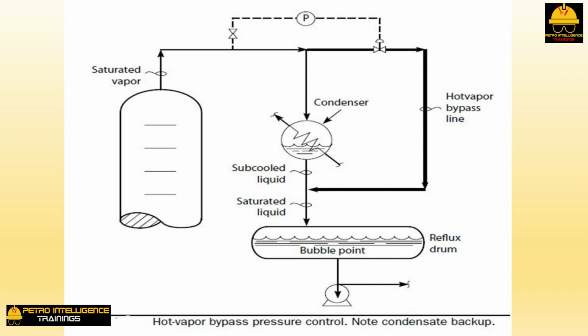Well, it cannot. The tower overhead vapor, shown in picture, condenses to a liquid on the outside of the cold condenser tubes. The liquid drips off the tubes. These droplets of liquid are in close contact with the saturated vapor in the condenser shell. This means that the liquid is in equilibrium with the vapor. The condensed liquid is therefore initially at its bubble point temperature. This liquid accumulates in the bottom of the condenser's shell. The submerged tubes then must subcool this liquid.